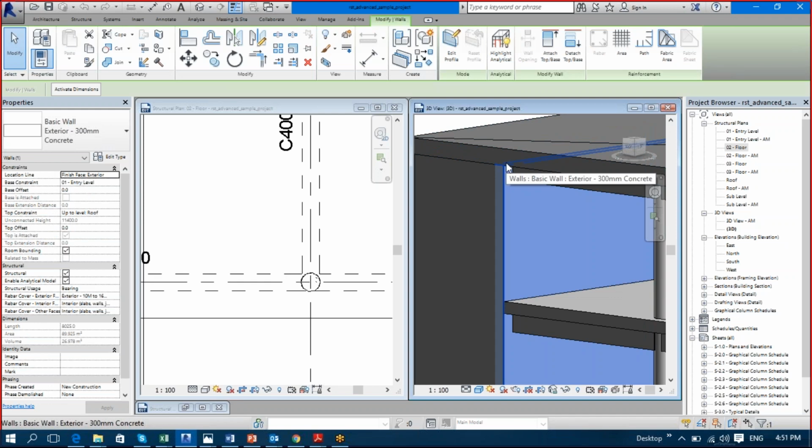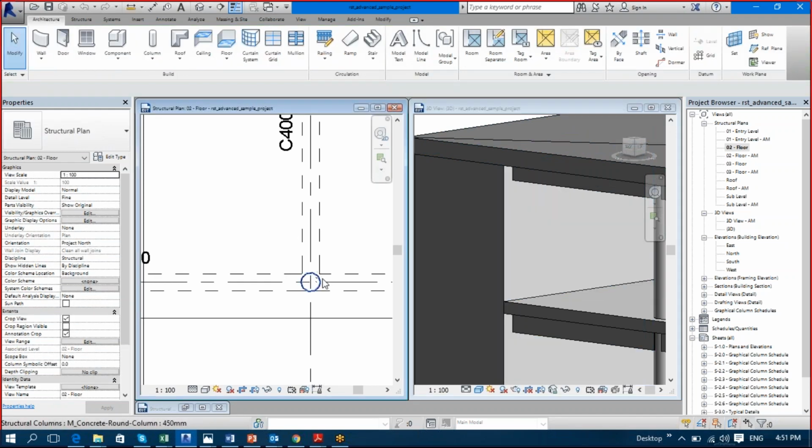This is a way of letting you know how to click that stuff. Now if some things happen like this, and I don't want to select this column, I want to select the wall by keeping my mouse pointer over there only. So the pre-highlighting will get circulated, and once you see what you want pre-highlighted, then you select it.